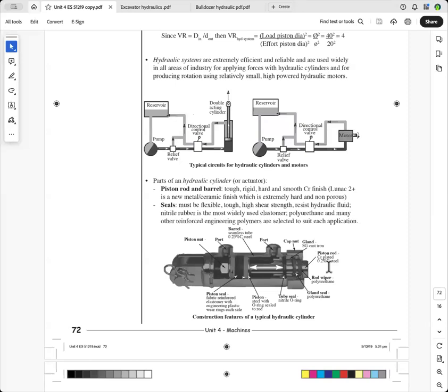This is a typical hydraulic cylinder. So this is a fairly small one. So there's the piston, and you can see these piston seals. When I see you, I'll be bringing one up to show you how it works, and I'll just quickly show you how they work. So you've got the seal that's like this, and it is tapered.